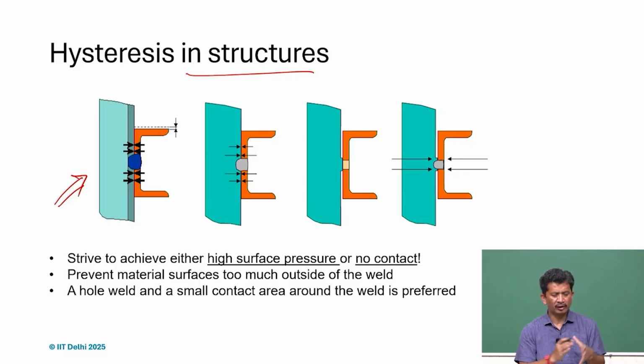The key point is, if the stress distribution is very large, so in some places we have high stresses, but in some places it's very small, there is a gradient, and once welded and coming to the normal temperature, there will be shrinkage.